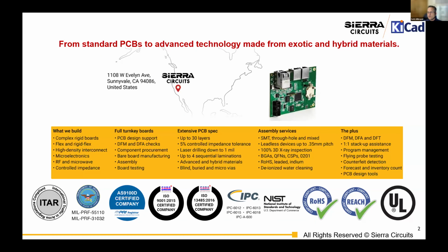In order to allow for fabrication, the paste mask for the SMD pad was split so that there was a gap that split across the hole.